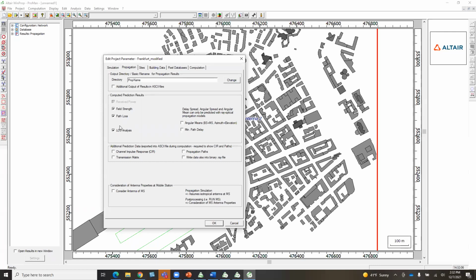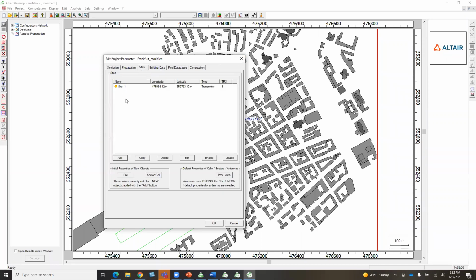So really being able to understand what's happening in terms of our wave propagation and field strength of these antennas. If I go to sites, you'll see all the sites I've created. You could actually manually create a site within here too, but I typically always am going to revert to the actual site boundary condition within Winprop. But it's nice to have different areas of how you access or make these changes accordingly.